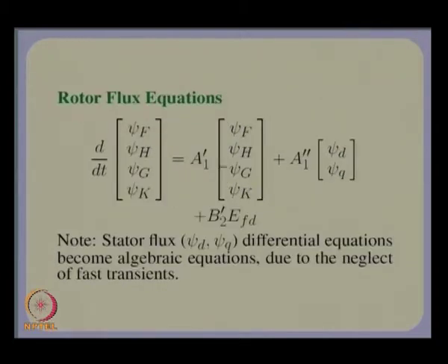These are the rotor flux equations. Remember that psi d and psi q are no longer states, so we do not have to write the differential equation for psi d and psi q. So, the only differential equations as far as the flux equations are concerned are the rotor flux equations.